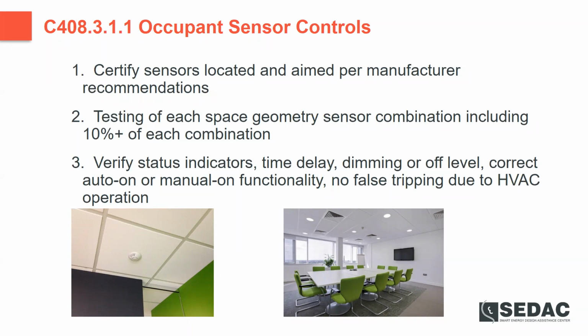And then verifying the status indicators, time delays, and all that are working properly, and there's no false tripping due to HVAC operation or other equipment within the space. So that, again, that sensor is only triggering based on occupants being in that area.